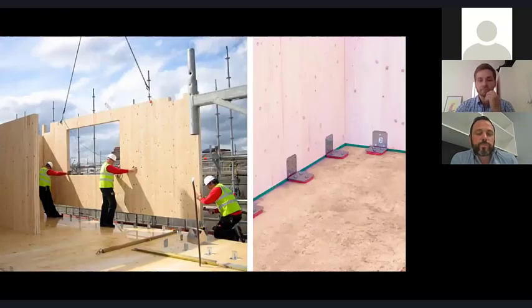Yeah, and look, this image was put on. This is more of the European approach. Now, look, I don't know the earthquake requirements at this location, but when CLT first came to Australia, the go-to was this type of bracket. And pre-installing the bracket and having them at certain centres was the go-to. And I really feel that the work we did at South Bank with Vistek really helped challenge that and just made you think a bit differently with the need of, are these connections needed? If they are, they're fantastic, they can work well, but are there ways of actually reducing it with more efficient ways of connecting?